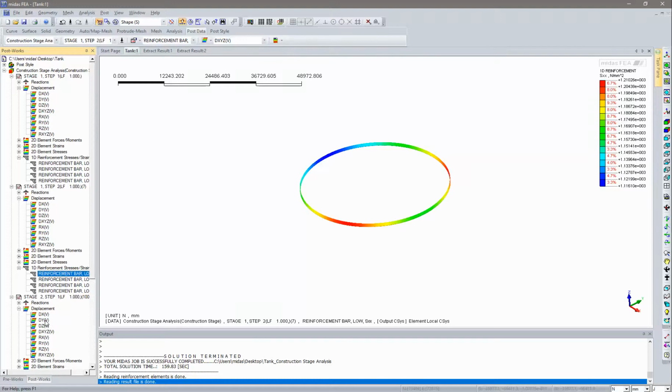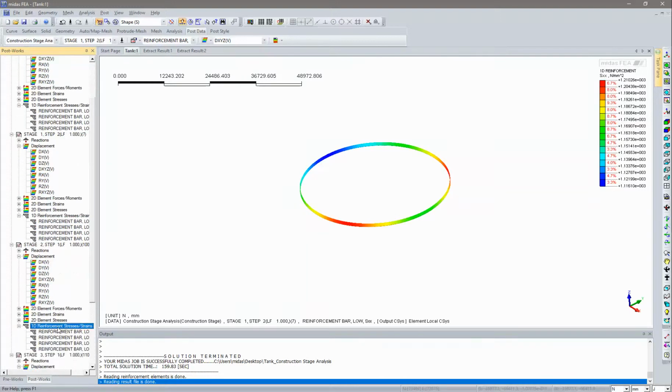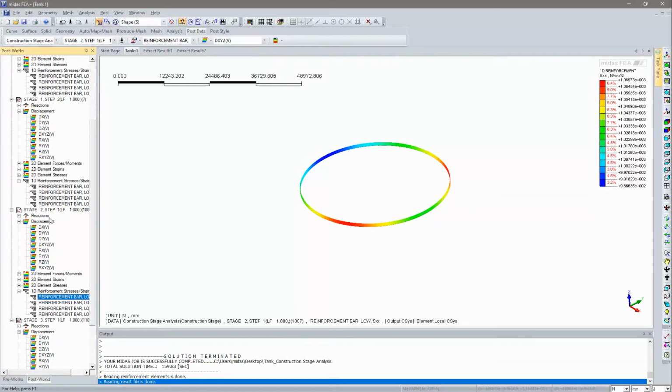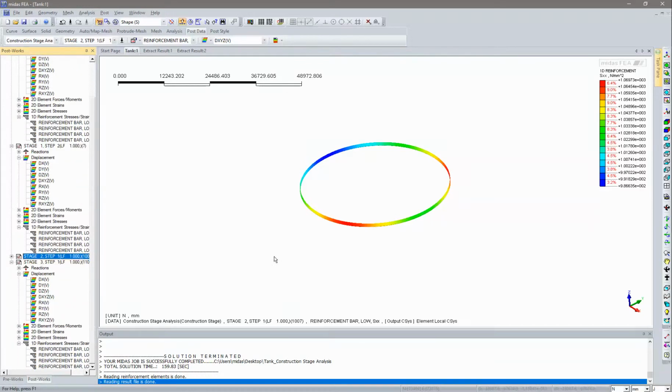Now let's go to stage 2 stresses. It has reduced even more. From 1200 it is now 1000. Here it is 980. This is due to the time duration and different time dependent properties, so the stresses in tendons are reduced. Now let's go to the final stage, that is after 10,000 days. It is around 970 to 890. So that is for graphical viewing of stresses.